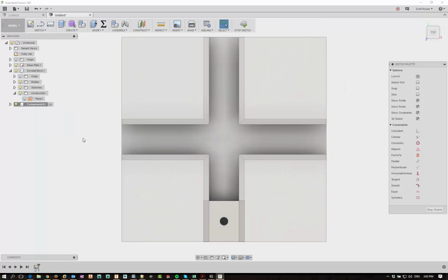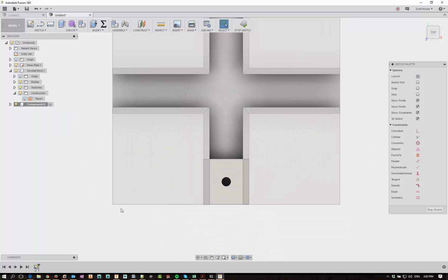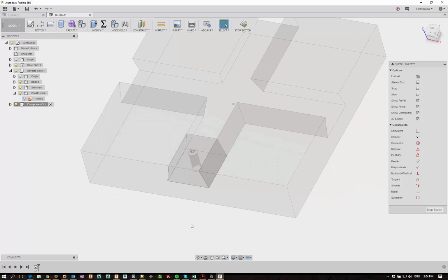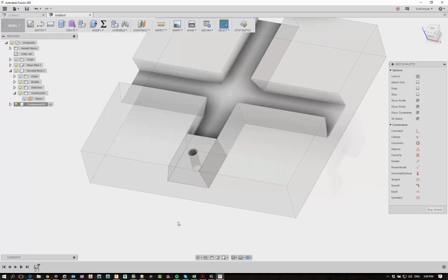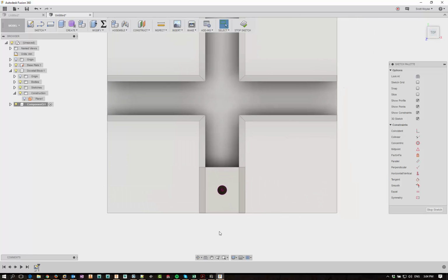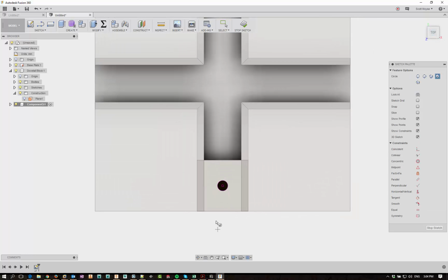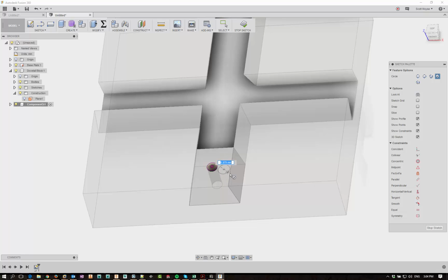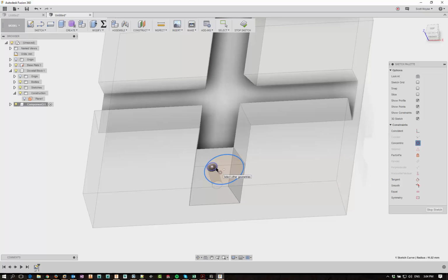That's the beauty of Fusion. And I don't want to use this sketch reference because I want to make sure that when things change, it uses the model geometry, not the sketch origins. Okay, and that's going to maintain my 6mm there as well. So now I can go circle, and I'm just going to draw one off to the side here, and again just to make sure that it's tied to the circle that I've brought through, and dimension this out 60mm.